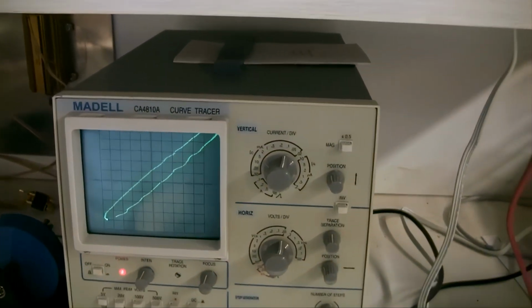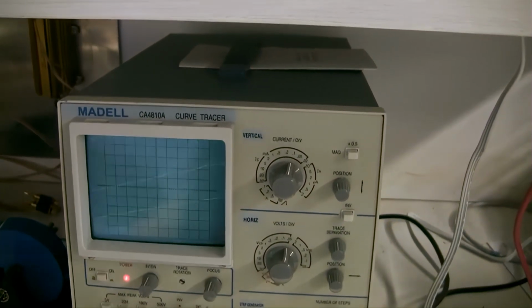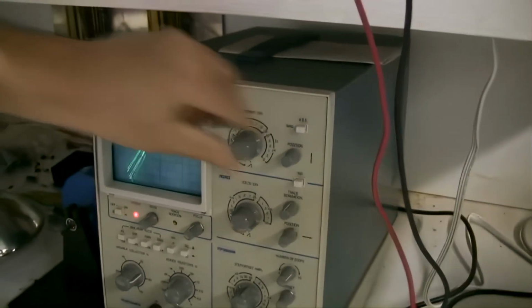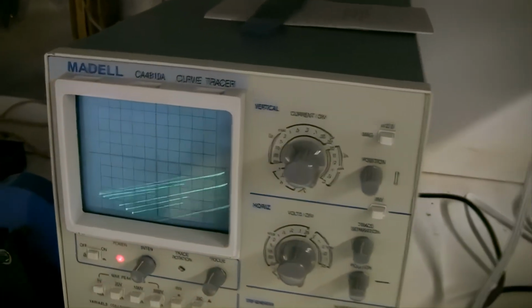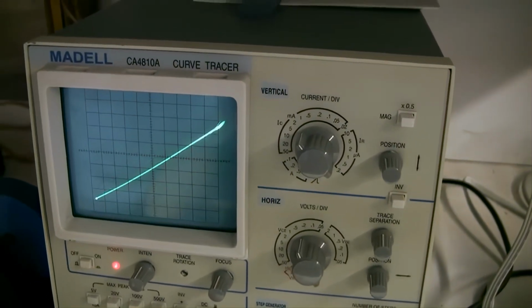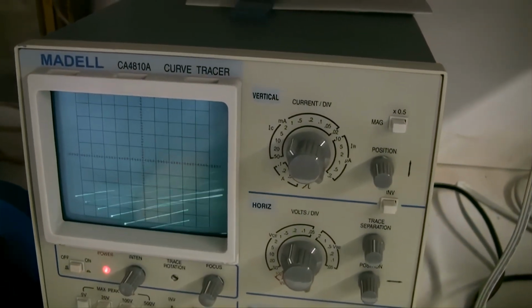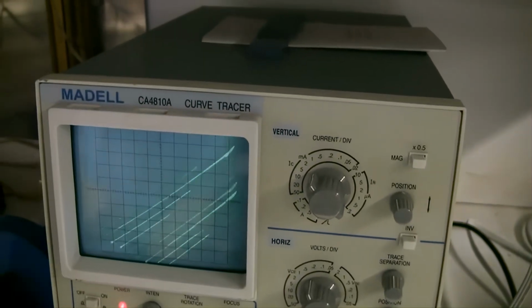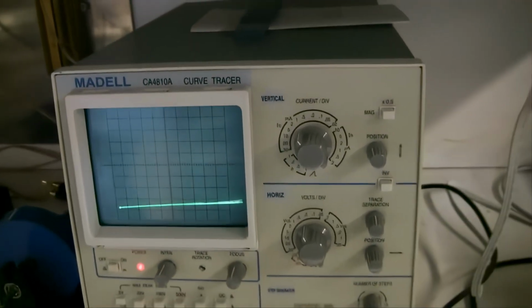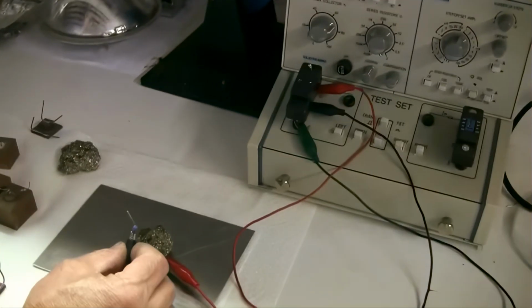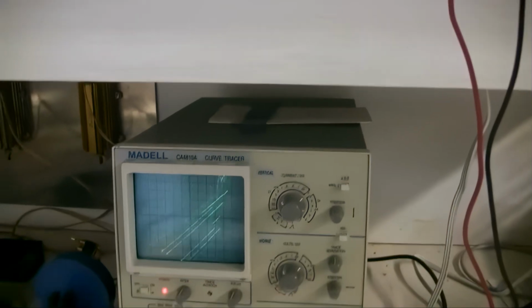See, because as soon as I get it here, see? I can tailor my semiconductor here by making a point contact out of this. So I could actually grind this, grind a point contact, come down and stick it on it, and I'd always have this device. And as long as I did them all the same, on the same machine, precisely, I would have this semiconductive device each time.